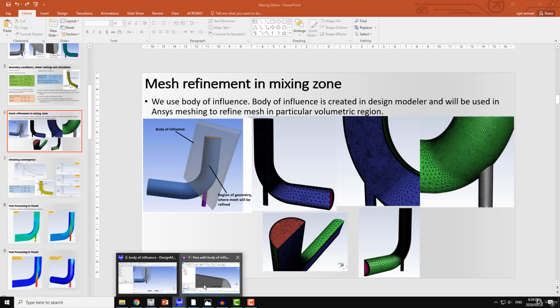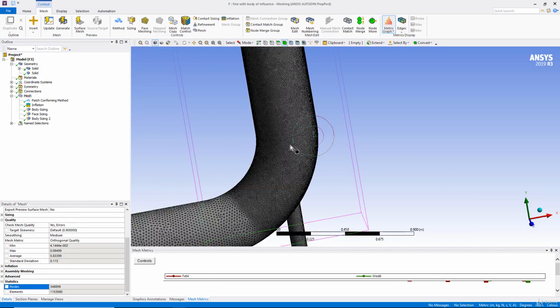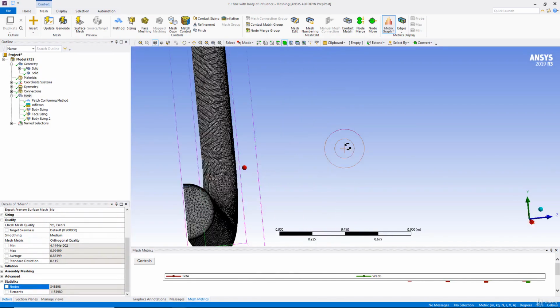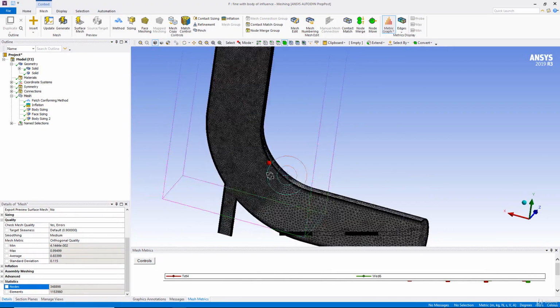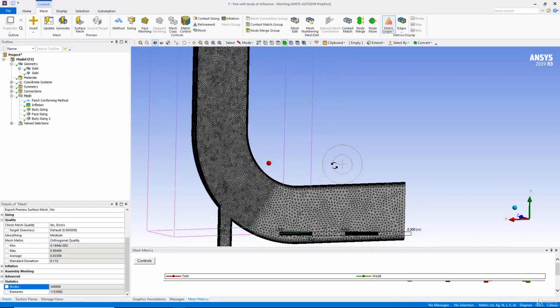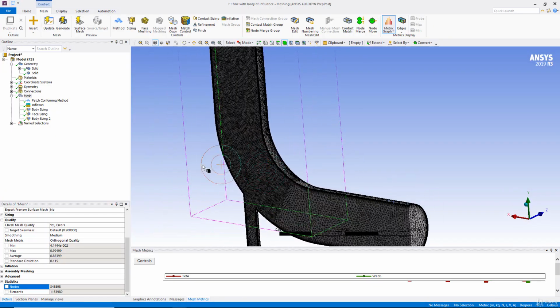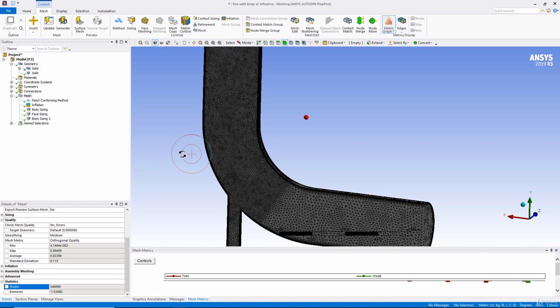But in the case of the very fine mesh, we'll proceed with all 4 meshes in the Fluent section and compare them one by one and see how the results are changing with the mesh. And again I will reiterate that once the mesh size has been defined, results are not changing. So we will go for the mesh with the larger size where the results are not changing much, and we call this a mesh independent